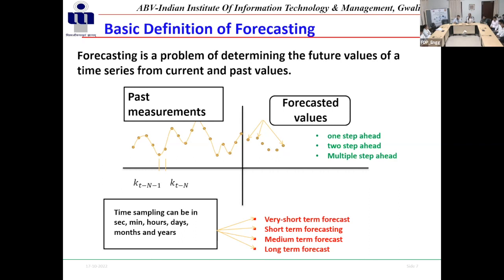Suppose I know the load forecast, what will be the load in this Agra city after 5 years? That is a big challenge. Why is it required? Because then I can plan what will be the requirement of transformers, cabling, and generating power stations if required. All these things are required for planning. Very short and short term we require for the operation purpose, because I have to deliver quickly. We cannot take time to plan and dig the roads and put the cables. So there are very short, short, medium, and long term forecasts.